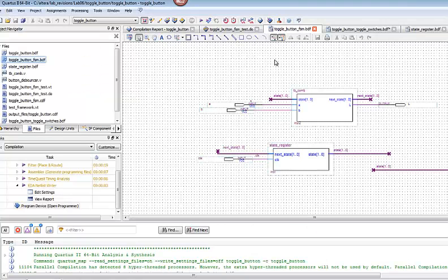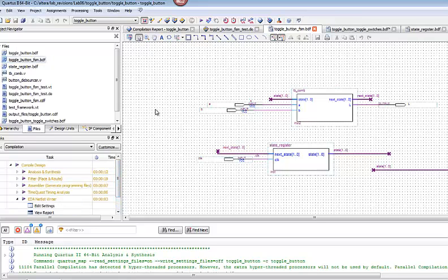All right, now we're going back to Quartus. We want to go ahead and run the compilation, and of course you should get errors for your ModelSim because you haven't added the equations. Once you've gotten it to actually compile with errors, then you can go back and write the equations. I recommend that you do it a little bit at a time to get it working a little bit at a time. You want to make sure that your states are working properly, okay?